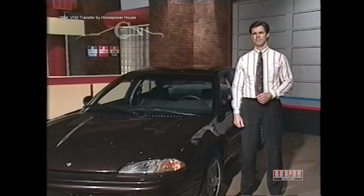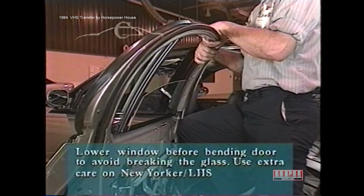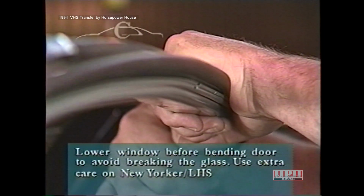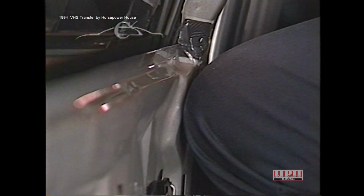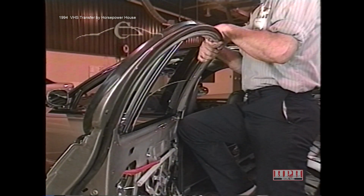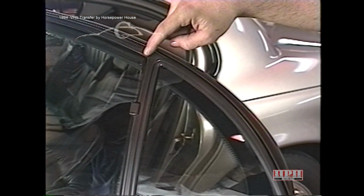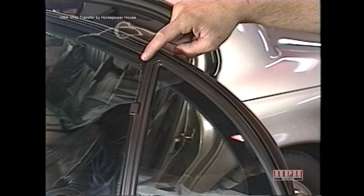Similar to the front doors, if wind noise is present at the top edge of the door, carefully bend the upper door inward using very little pressure. As always, lower the glass before performing this procedure, and be particularly careful when performing this procedure on the larger doors of the New Yorker or LHS. Again, striker or hinge adjustment may be required after this procedure. If wind noise is present at the top of the rear door windows on New Yorker or LHS models, check to make sure the window glass is properly seating inside the weather strip.